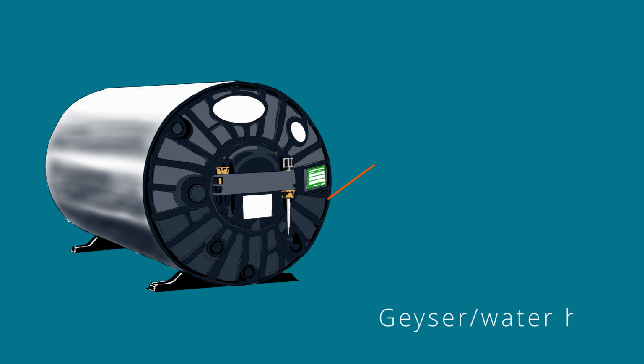Now, if you know these types of calculations, then you are able to calculate roughly how much you spend on your water heater each day. If electricity costs, say, 11 cents per kilowatt hour or per unit in your country or in your state, then you can calculate roughly how much you are spending to keep that water heater running each day.